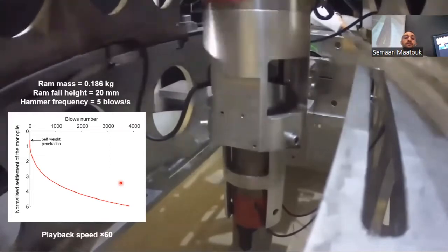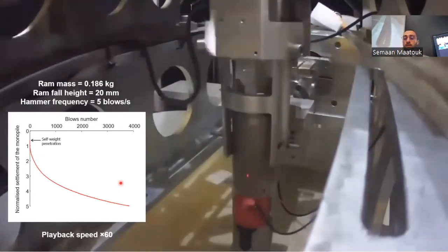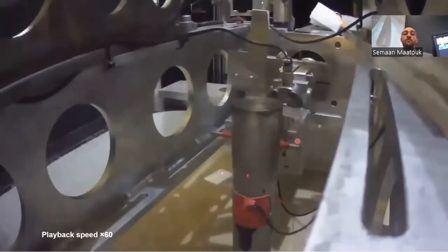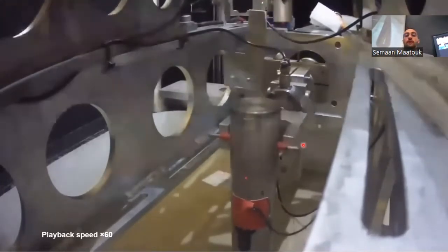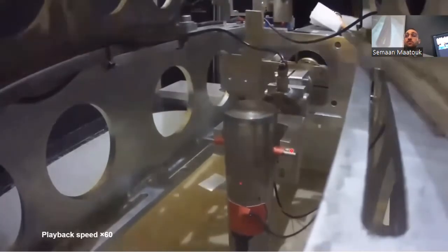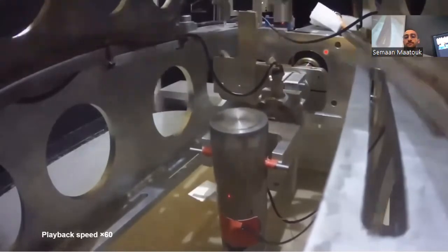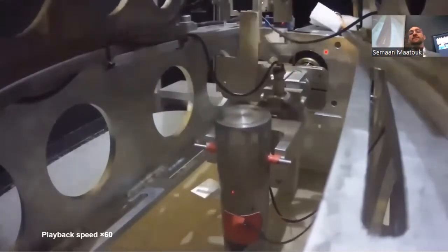Then I removed the vertical system in order to laterally load the monopile horizontally with a displacement control by pushing the steel rod that crosses the monopile through a fork that is attached to an electric actuator. And finally, I released the fork.